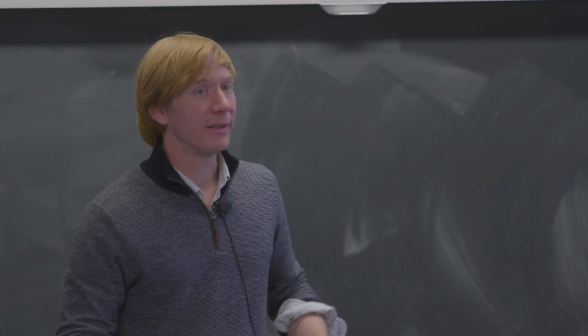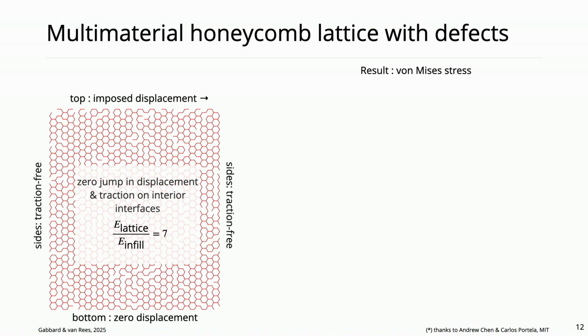And so Carlos helped us come up with a sort of a complex problem. This is a honeycomb lattice with defects. Carlos and Andrew Chan, his student, and we applied our method to this problem. There's a zero displacement on the bottom and imposed shear at the top, traction free at the sides. Those are the boundary conditions on the outside.